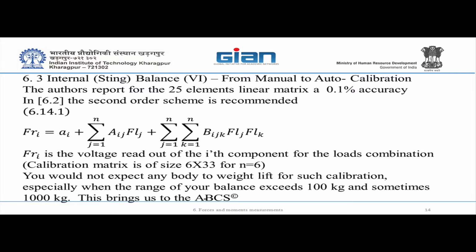Those days we were looking for some electromechanical machine. You connect the balance to the machine, and it will be loaded by kind of hydraulic actuators, and load cells will measure, so you know exactly what you are loading and what you are measuring, and you can have as many points as you like in considerable reasonable time.